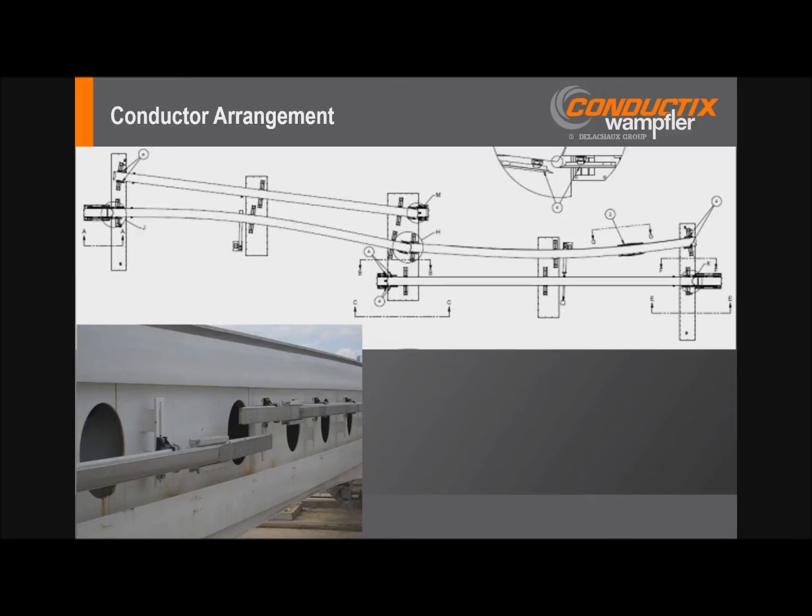The effects of short circuit loads are typically not a big concern for DC systems on monorails because the positive and negative conductors are on opposite sides of the beam. The spacing generally reduces those forces to certainly well within the capacity of the hangers and the splice in the conductor bar. Now for AC systems, the conductors may be on as little as 3-inch or 75, 80 millimeter centers, so fault conditions may be important. It's important to take a look at what the resultant loads will be on the adjacent AC conductors in a fault condition.